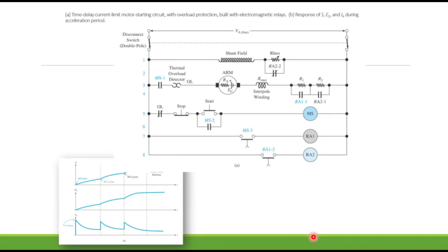Here is a starting circuit, typical starting circuit of a motor. Let's take a look at this. Here's my line coming in, and I've got a switch. This dotted line, if you recall, represents mechanical coupling. So whenever one of these switches is thrown, this disconnect, they're both acting in tandem. So we put power on, and that supplies current through this rung of this diagram. And it looks to me like current's going to flow. It's going to be limited a little bit by this variable resistor.